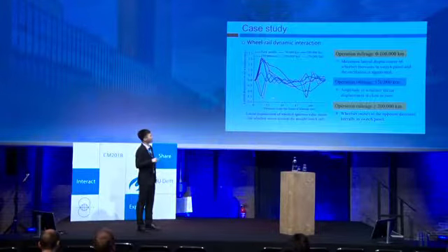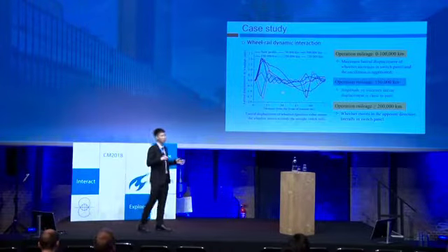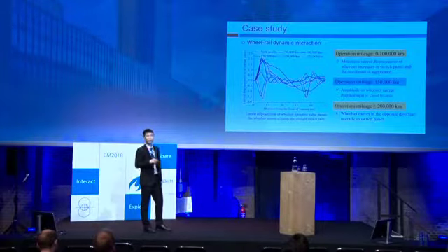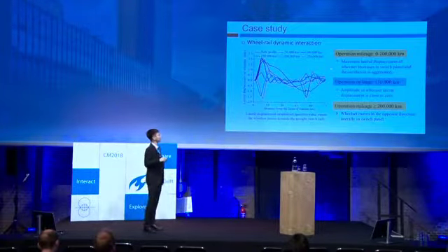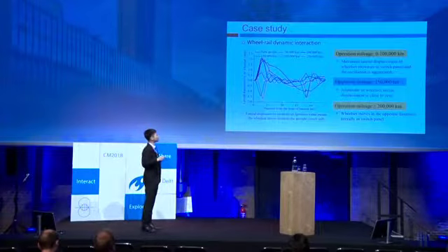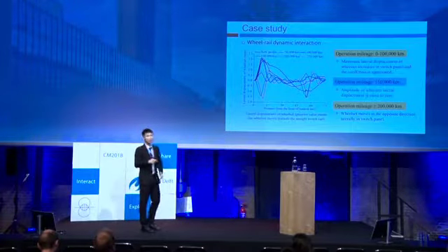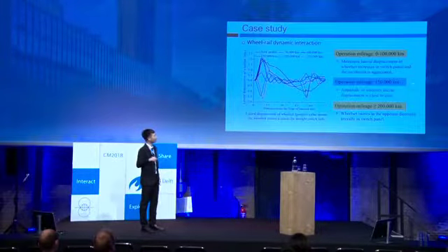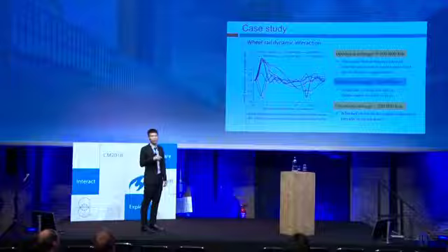As far as the lateral displacement of the wheel set, this figure shows the simulation results. The positive value means that the wheel set will move towards the straight switch rail side. It is found that when the operation mileage is below 100,000 kilometers, the maximum lateral displacement of the wheel set increases in the switch panel, and the acceleration is accelerated. When the operation mileage reaches 150,000 kilometers, the amplitude is close to 0.